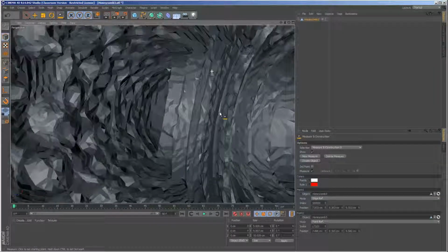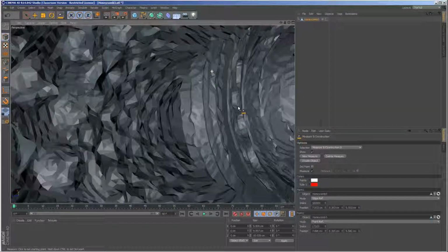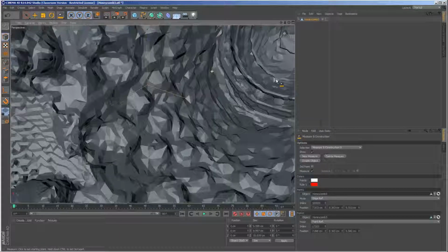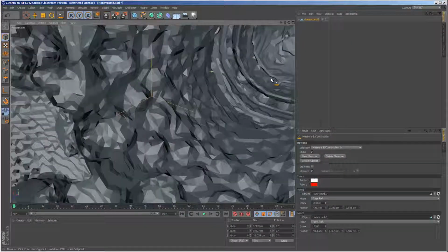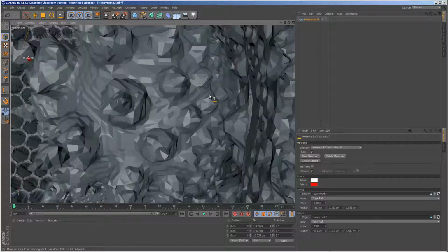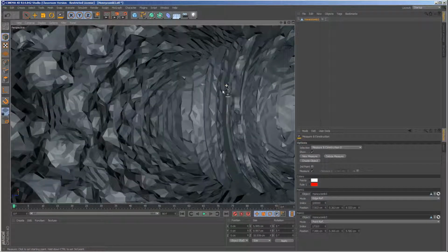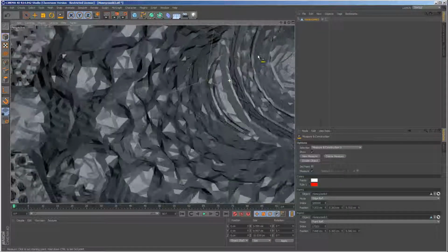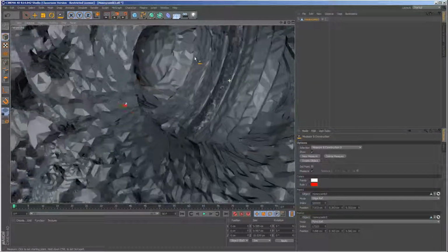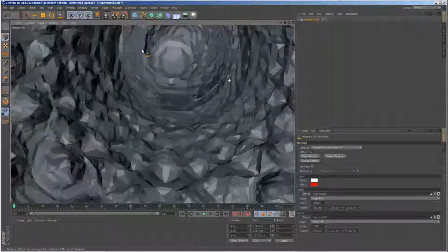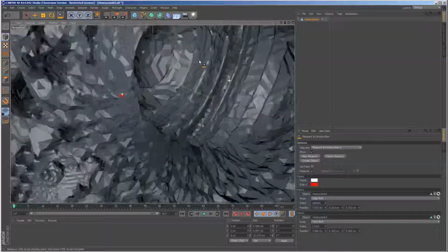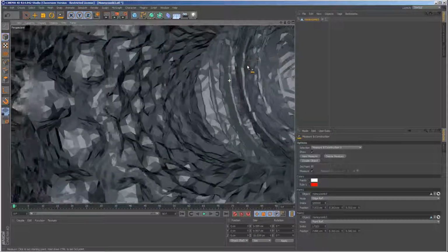Some of these will be solid objects floating inside of other solid objects. Some will be loose powder. But this also is the reason why there's so many polygons in this model, is that it's all of these shells inside of shells. And I have a feeling that this is going to prevent this from printing, as I zoom in through the model, you can see all of these extra shells.